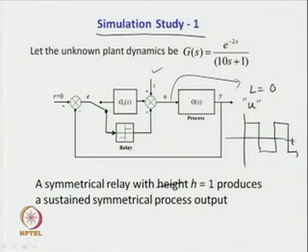So, this is what we have, T and this is our u(t). This is what we get when L is equal to 0, when the static load disturbance is equal to 0. Suppose L is of some magnitude and the relay amplitude is 1, therefore, magnitude of this signal is equal to 1. Now, when L is equal to 0.5, then this 0.5 will get superimposed with this signal and ultimately it will get elevated.